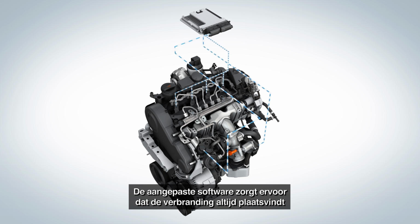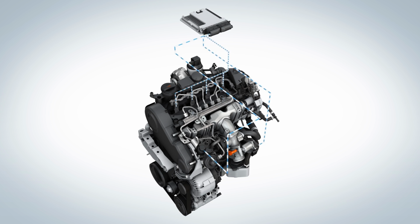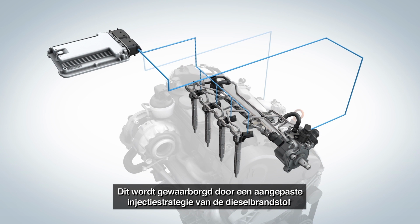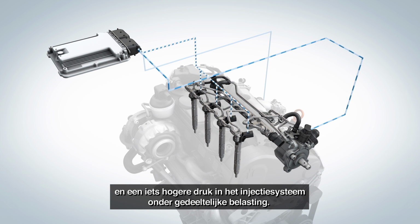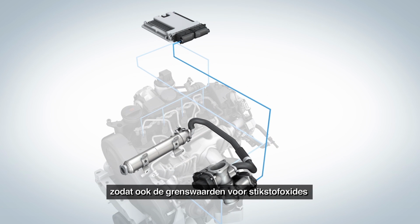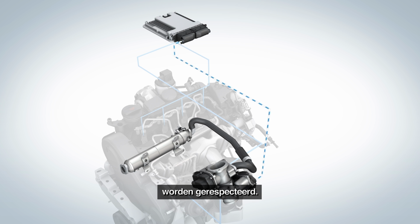The adapted software ensures that the combustion is always carried out in a NOx-optimized mode. This is ensured by a modified strategy of the diesel injection and a slightly increased pressure in the injection system at partial load. In addition, the exhaust gas recirculation rate is optimally adjusted, which also ensures that nitrogen oxide's test limits continue to be met.